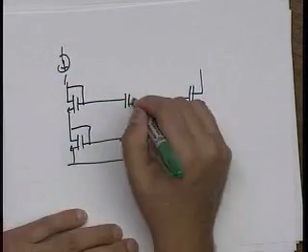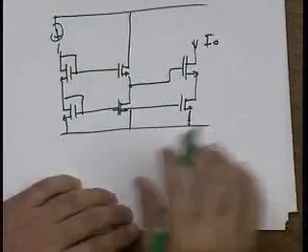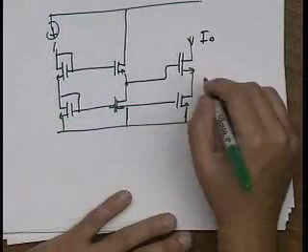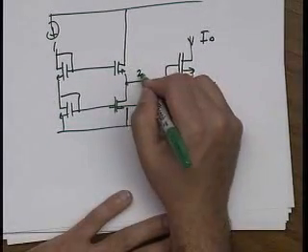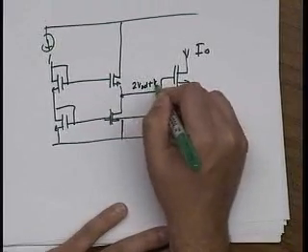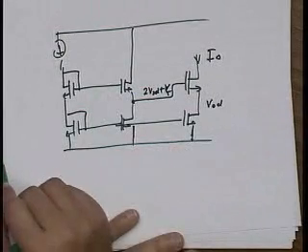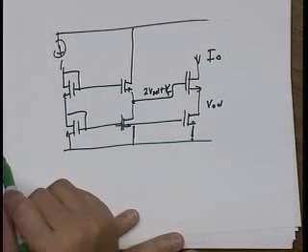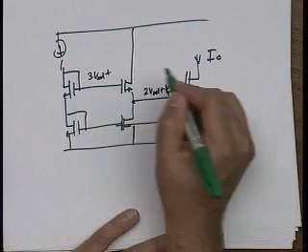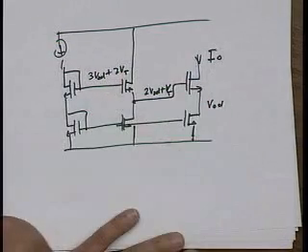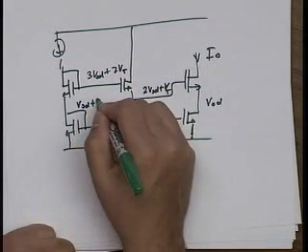It's diode connected. This is my output. And again, I want this voltage here to be overdrive. This voltage here to be 2 overdrive plus a VT. If I add another VGS here, if these W over L's are the same for all the circuits, then I get 3 overdrive plus 2 VT. Okay? And this point, of course, is also at V overdrive plus VT.